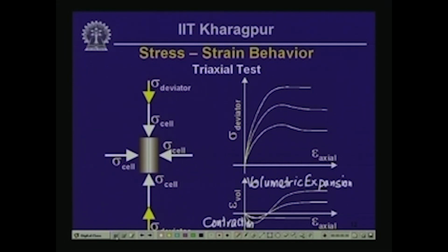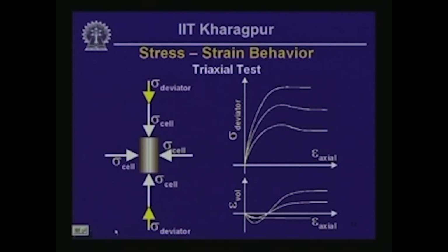Based on this, we are going to plot the Mohr circle concerning the stress condition in these triaxial tests, and we will be trying to identify the strength parameters from this series of testing of three cylindrical samples of soil or rock mass or intact rock.